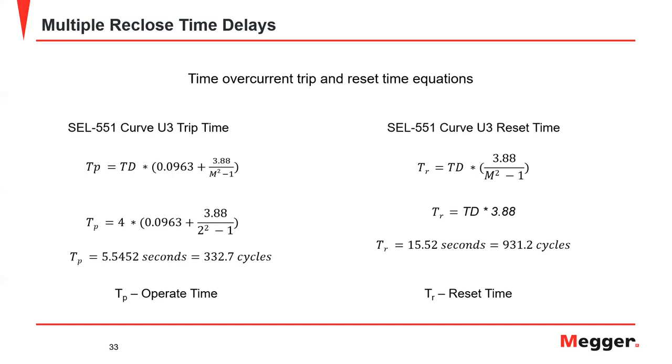In some cases, you sense voltage on one side, let's say on the load side, and sense voltage on the line in order to verify that there will be proper synchronization when you're doing the reclose, just in case you have some sort of feedback from the other side.